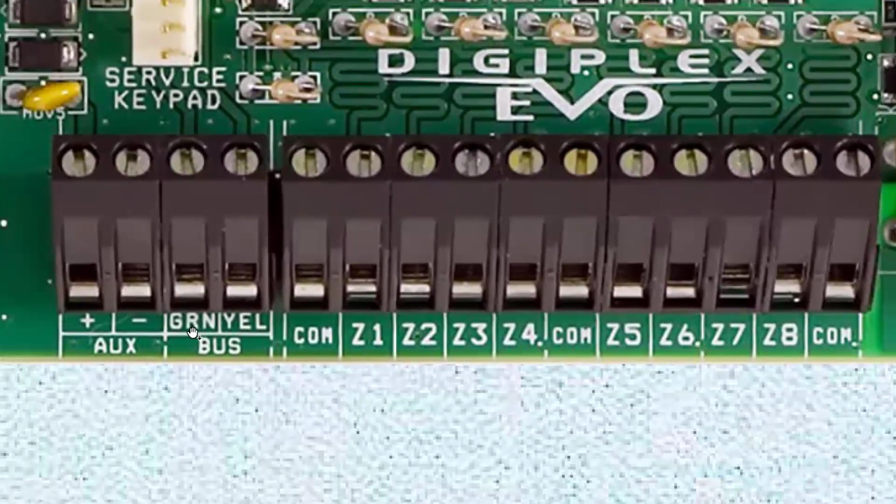Let's go. Here's the bus. Okay, look, this was in green and yellow. Something that's called a quad cable is usually used to wire up the devices in security alarms. And the quad cable uses the old color code: red, green, black, and yellow. Except, as opposed to telephony, we're not using the red, green, and black and yellow. We're using black and red out of this 4, and quad because it's 4 conductors. We're using black and red for the power, and we're using green and yellow for signal